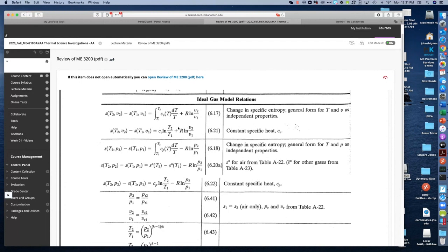The second term of entropy needs a little bit of discussion. Here you see that if the volume increases as we go from state 1 to state 2, an increasing volume means that the system is going to a more open, a more random, a larger state. And so that makes sense that this term here gives rise to an increase in the entropy.